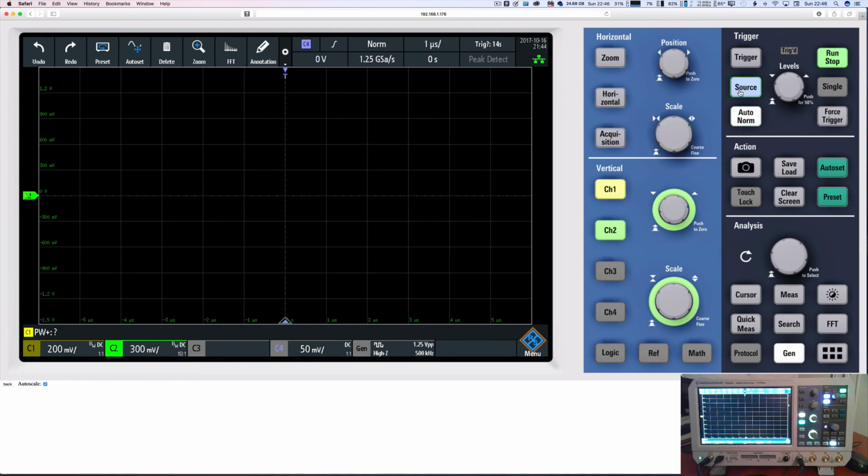But I believe, and I will confirm this, I'm pretty sure I could actually trigger when the channel's not actually on, so it's still reading from the last setup as such, but you don't have to have the display on, which I proved on a protocol before when I did one of my last videos. I will check that out, but effectively what I'm saying is it would still be looking for a trigger signal from the blue channel. So if I had a splitter on this and I was sending our generator signal not just into 1 but into 3, I could set up 3 for the correct trigger signal, let's say the correct voltage, and select it here, and we'd actually be triggering off that, although we weren't displaying the waveform. It might just look odd, but I think that's the way it works.